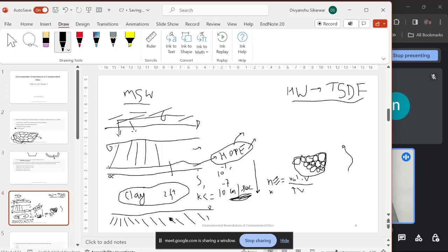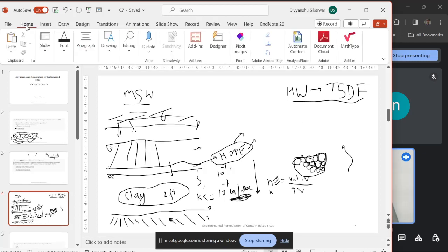If the layer gets damaged, the leachate will travel through clay. Clay will be the only barrier present which prevents leachate from going into the subsoil. So there is no detection. We can't detect here. But for that there is another system called double liner.